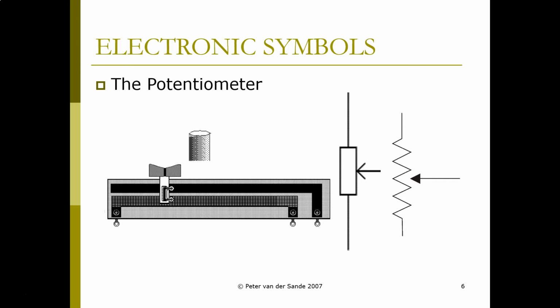The other way a potentiometer is built is in a linear or slider fashion. If you look at this one, the left and the center over on the right-hand side, the left and center leads represent the level of the resistance from the left side to the right side. And then the third ring or terminal is the slider. As you move the knob to the left and the right, it slides along the resistive material, allowing you to vary the resistance as you slide from left to right.